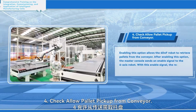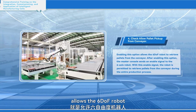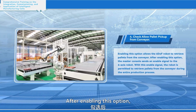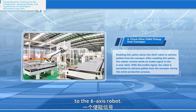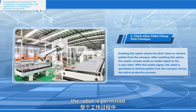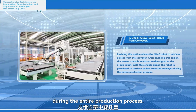4. Check Allow pallet pickup from conveyor. Enabling this option allows the 6DOF robot to retrieve pallets from the conveyor. After enabling this option, the master console sends an enable signal to the 6-axis robot. With this enable signal, the robot is permitted to retrieve pallets from the conveyor during the entire production process.